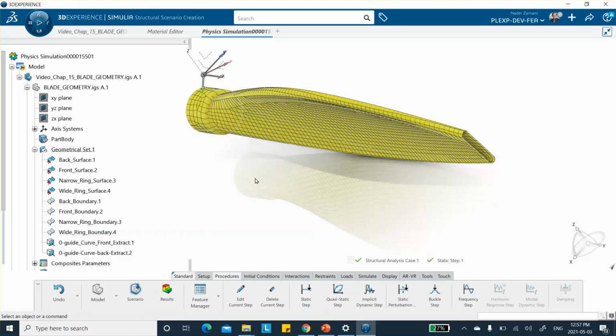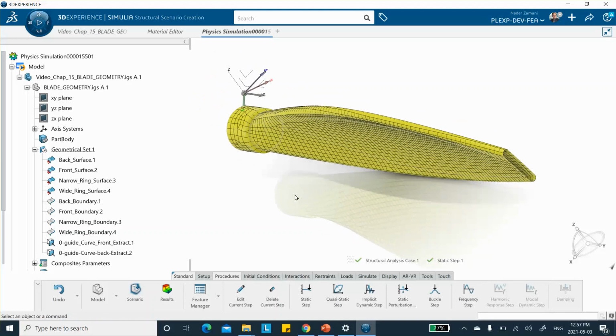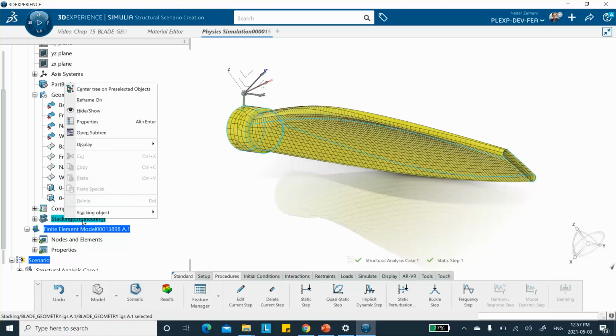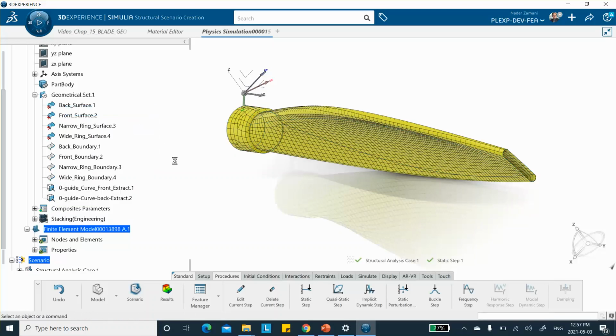Now we're going to apply our loads and restraint. Remember that I always tell you to hide a bunch of stuff here before, because you don't want to select a ply boundary instead of putting the clamp on an edge. So what you can do is hide the stack branch. But now when you select an edge here, it's truly an edge, okay?